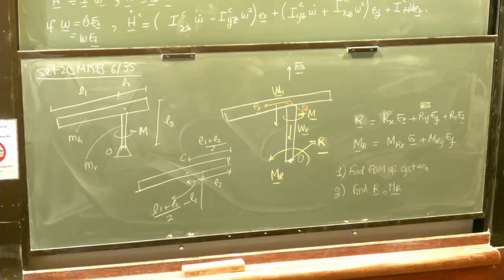Can I see how you're calculating the moment? I was kind of confused on how to do it for the weight. R cross F. The weight is applied here, so you have to find the position vector from the origin to there, and cross it with the weight. It has a vertical component and a horizontal component. The vertical component will cancel out eventually.